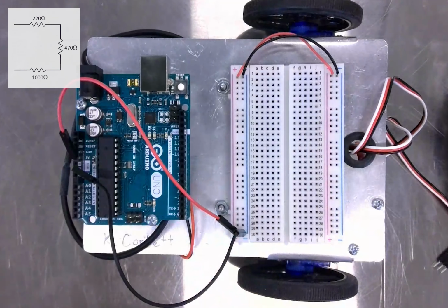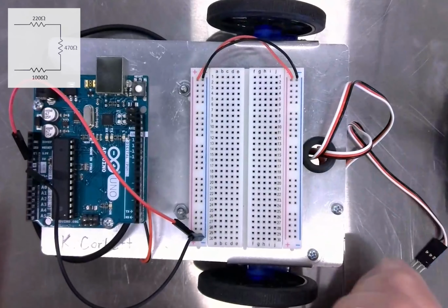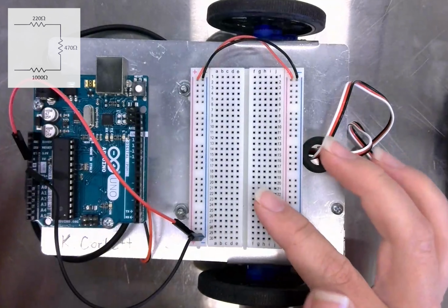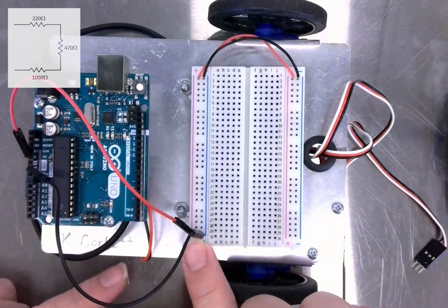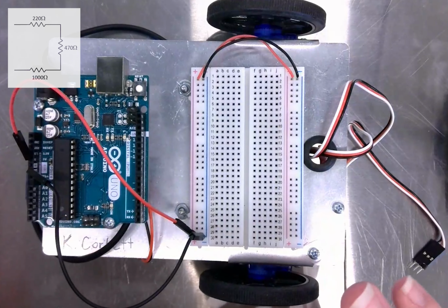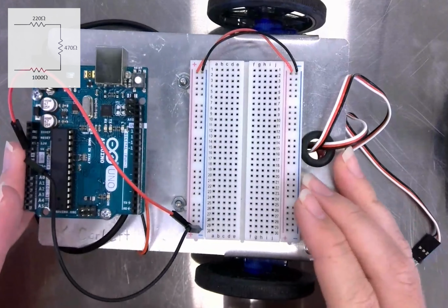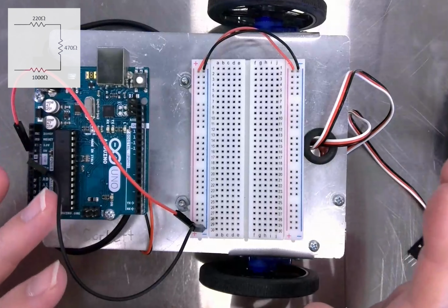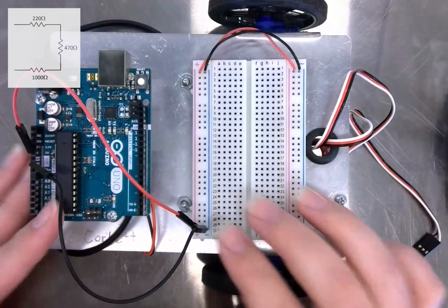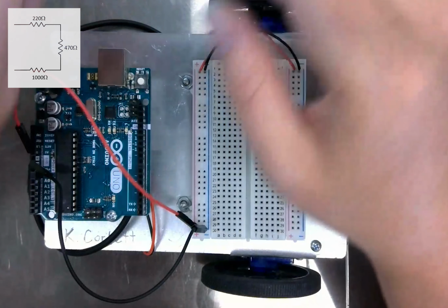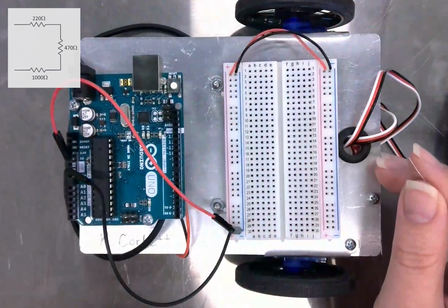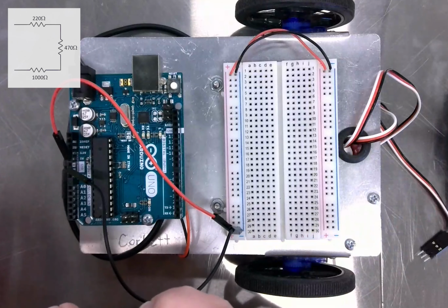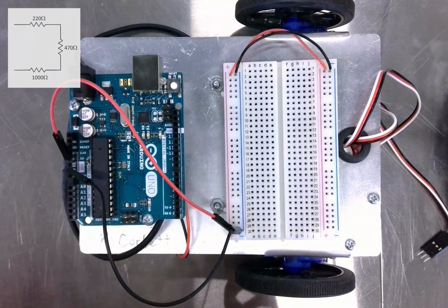Okay, once you have your resistors, let's go ahead and build them on the breadboard. Now, we are not going to use the power supply. We're not going to power these resistors. We want to measure the resistance, and you can't measure the resistance using your multimeter when they're connected to a power source. So we're going to start with and look at the resistor circuit diagram that I have showing on the screen, and we want to build that.